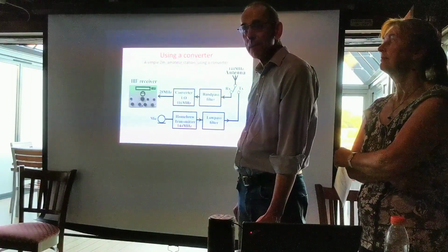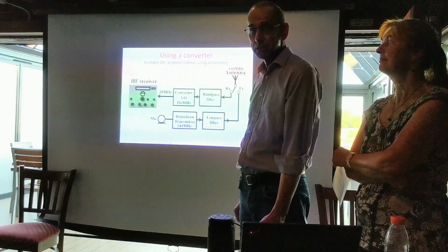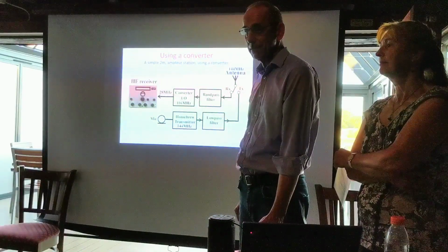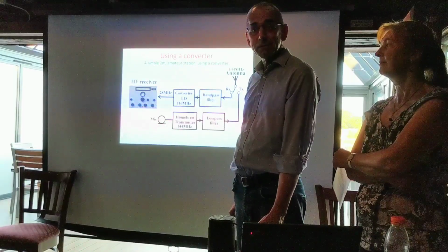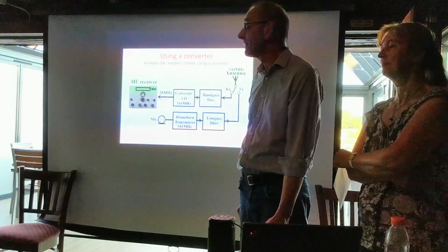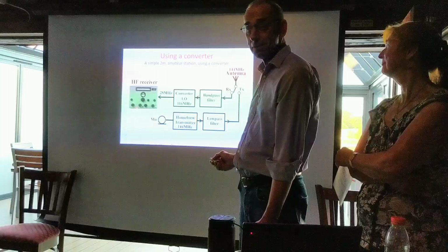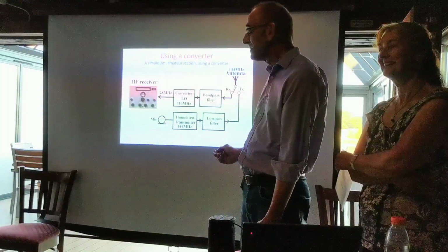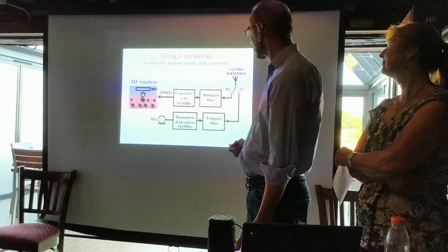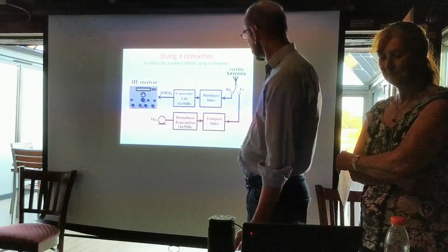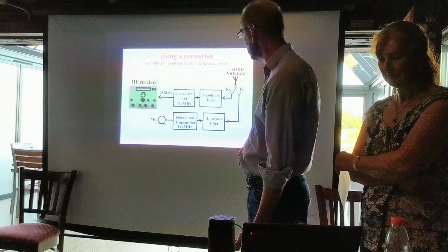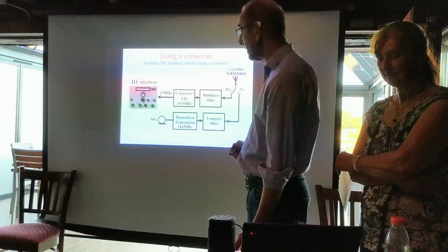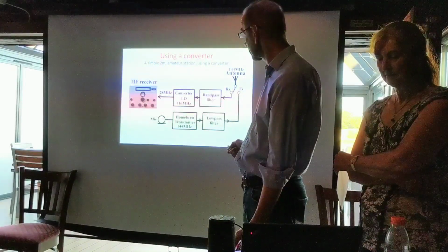But at the time, transceivers for the 2 metre band were very expensive and hard to get hold of. I didn't have the money, but Army surplus equipment was very cheap. So I had a CR100, which I can see Andrew laughing over, and I used a converter. Basically it took the 2 metre signal at 144 megahertz, mixed it with 116, and one of the results is 28.